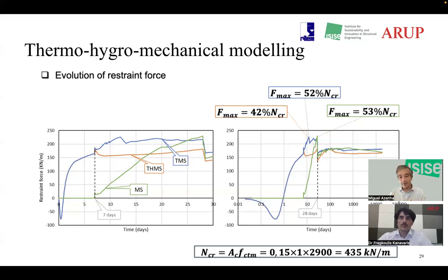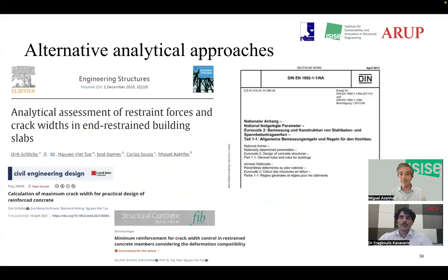And the bending, altogether with this, even has some beneficial factors together with the creep. And all of this together reaches something that allows us to save reinforcement. This is a very important conclusion that we are following up with further research, but it aligns with many designers that do this by intuition.